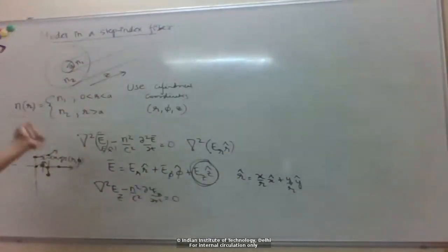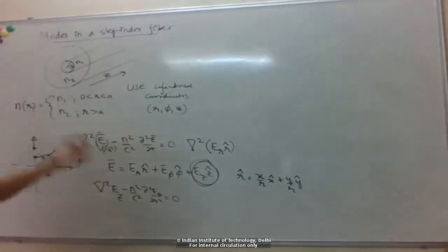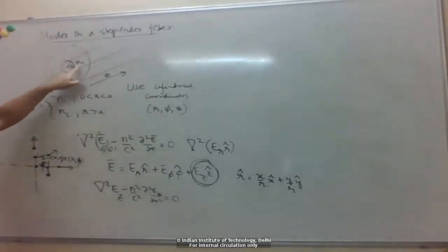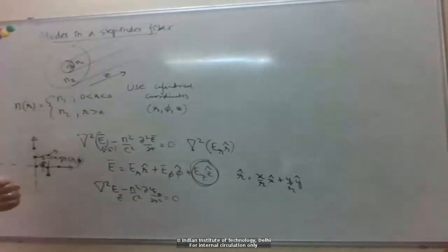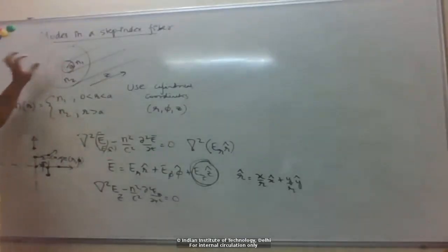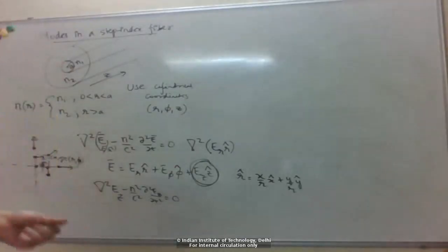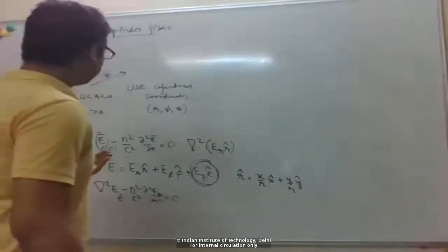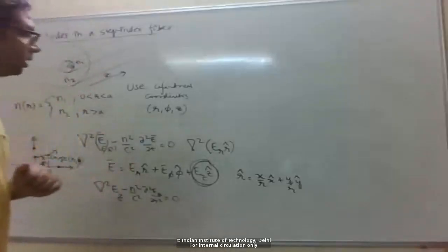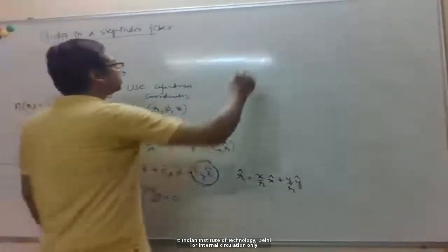But in most practical optical fibers, the index contrast, N1 and N2, are very close to each other. So that delta, which is the normalized index contrast, as we discussed, is very small. Maximum it usually goes to is 10 to the minus 2, usually it's in the 10 to the minus 3 range. Under this approximation, when the index contrast is very small, as we had discussed for example in slab waveguides, the modes can become almost transverse. So we saw this weakly guiding approximation.